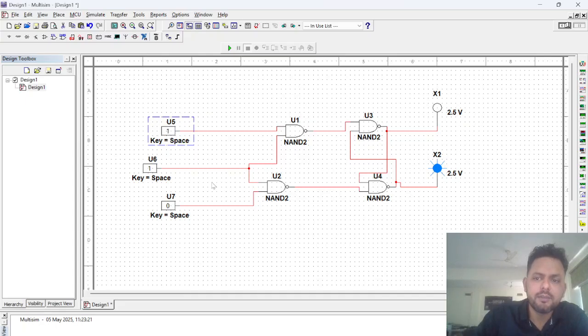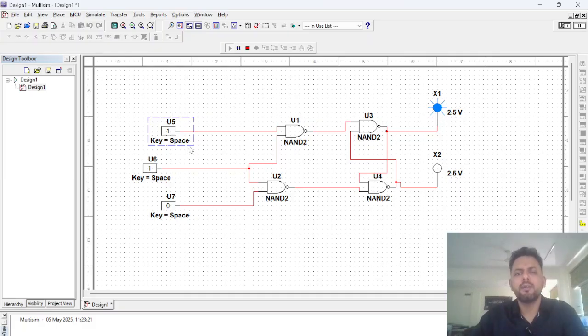But as soon as it is 1 0, okay, now just stop. See, 1 0, we get 1 0 out here, and this is 0 1, we get 0 1. But as soon as it becomes 0 0, it always gives you the memory, it will not change. See, it is not changing whatever the value you give. Or similarly, if it is 1 1, again it is memory, whatever is the memory, it will remain the same.